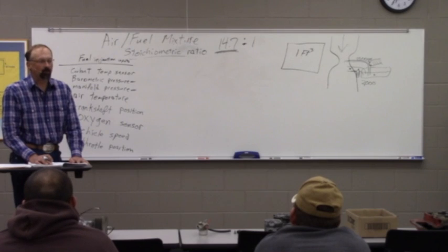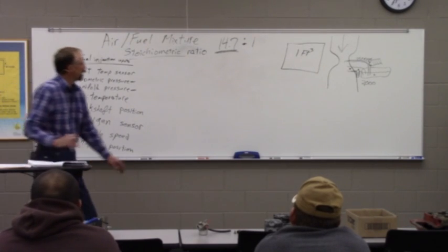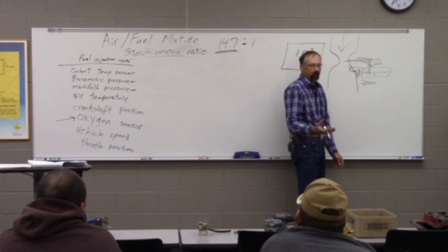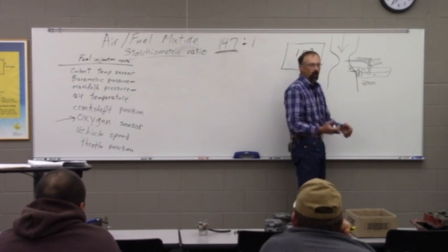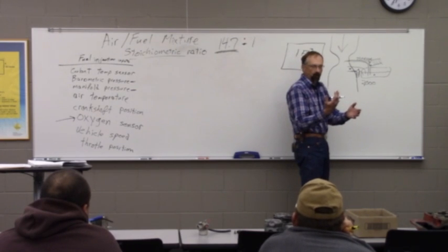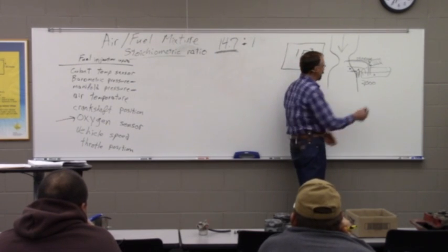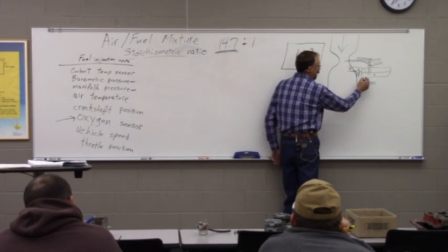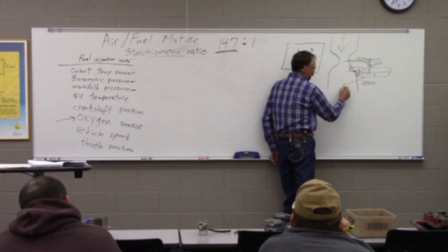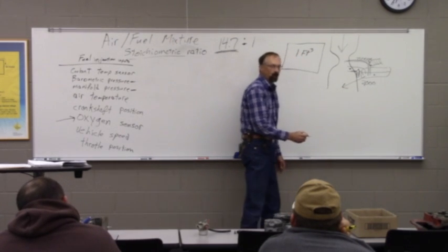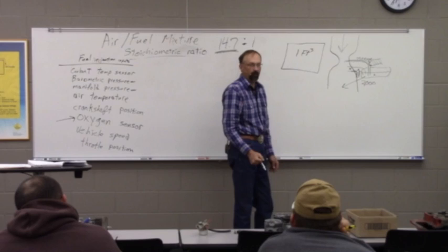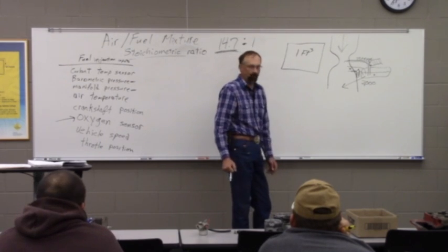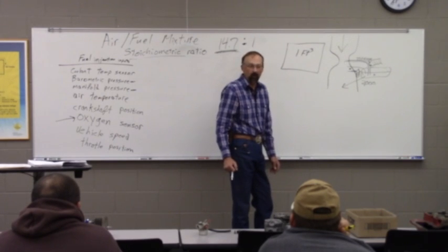Right. Because in the old carburetors, what we had over here was a device known as an accelerator pump. And what it did is, as you moved that throttle pedal down suddenly, it would take some of this, and through a small, typically diaphragm style pump, it would squirt some fuel right straight in there. And it helped enrichment, and a lot of times what you were doing was kind of making up for maybe a choke that wasn't working so good.